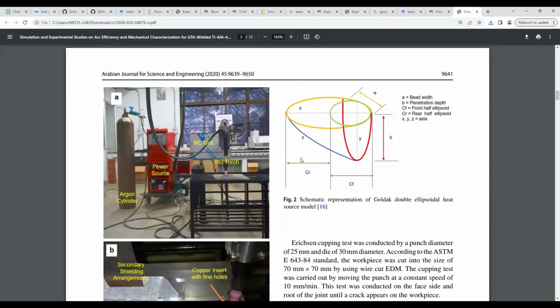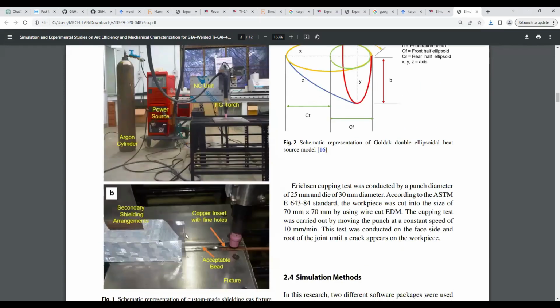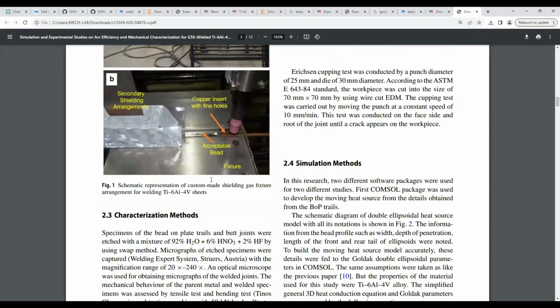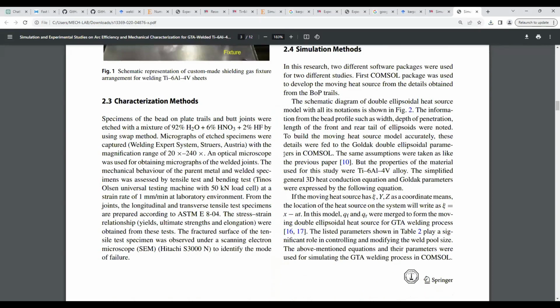Okay. So this is the setup which we have made. As you can see, the center portion only is clamping the specimen, whether you want to clamp the entire specimen or a particular portion. That is also possible in this software. And in other software, I don't think so. We just clamp on the perfect location only. But here, you can exactly create the dimensions of how it looks like in the fixtures. So 3-dimensional heat conduction and ellipsoidal source, heat source front and rear, overall heat input we have taken. Without efficiency also.